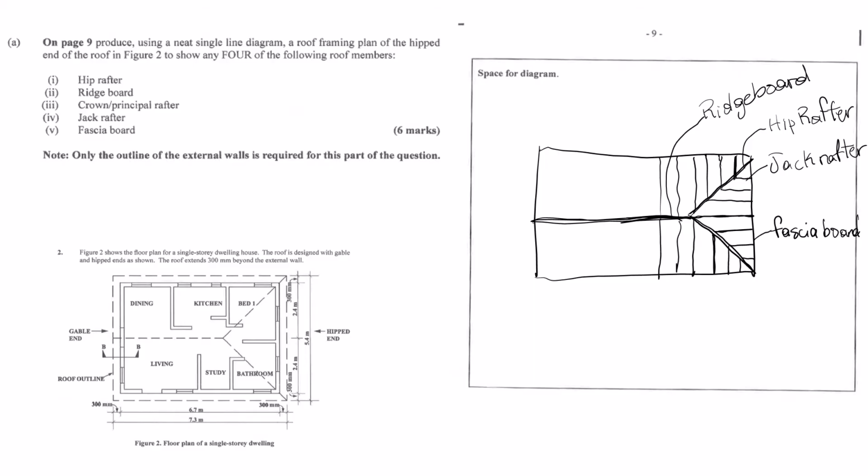And then there are jack rafters. What do they do? Jack rafters are shorter. We fill in the gaps, basically. They run between the hip rafters and either the ridge board up top or the wall plate down at the bottom edge. They don't go the full length like hip or common rafters. Think of them as filling out the roof structure in those triangular sections created by the hips. Okay, so they're like shorter ribs coming off the main hip structure.